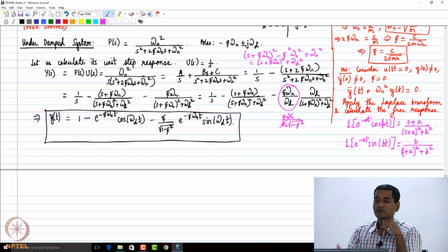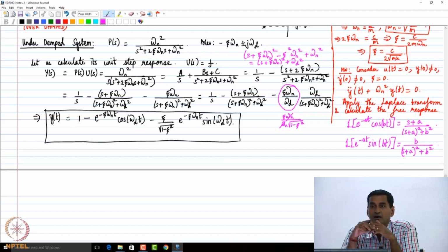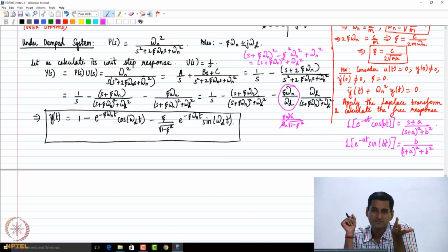Okay. So, immediately we can see that the expression which we derived is the unit step response of the underdamped second order system, right? And we can immediately see that it has two exponential terms. The exponential terms have the real part as the exponent. You can immediately observe that. Of course, in general, you can write cos omega d t and sin omega d t using Euler's relationship, and then you will see that the poles will be the exponent. Okay, that is also something you can do. So that is observation number one. So it is stable because the real part is negative.